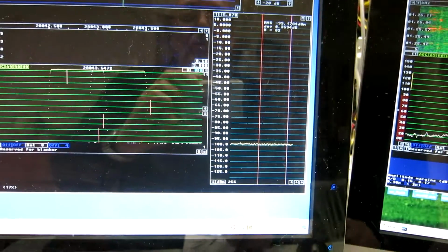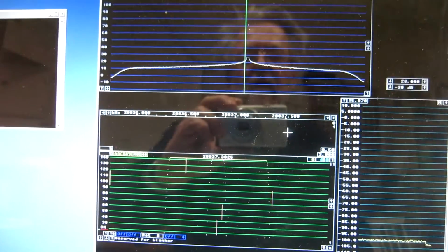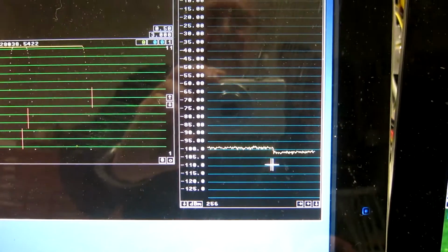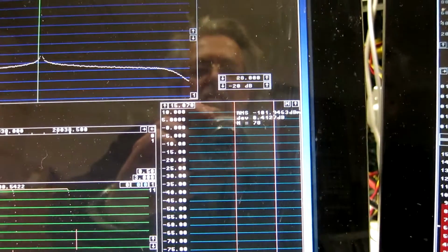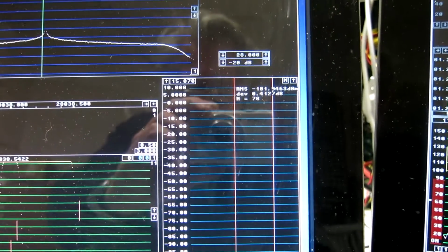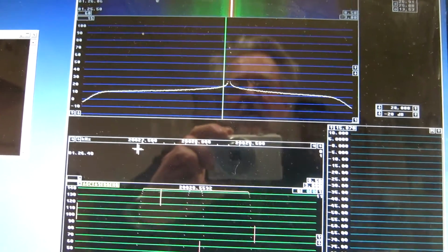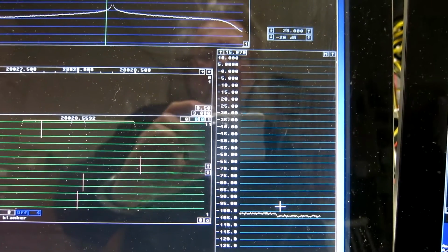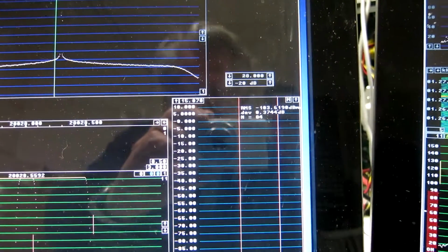99.2, and then I go 10 kHz below. That should be about here. 38 is what I want, so I click on 38 and then get the noise floor in 1 kHz bandwidth as minus 102 dBm. And then 20 kHz, that would be 28. That's here. And here the noise floor is minus 103.6.